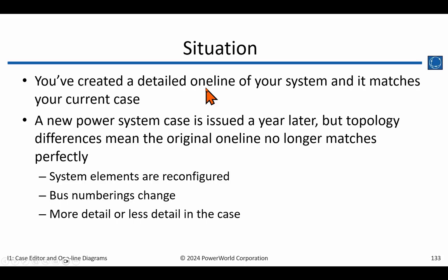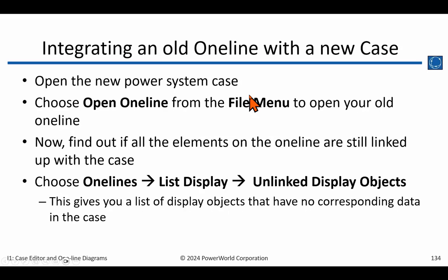Unfortunately, this is a situation that occurs pretty commonly with bus branch models. A holistic solution is to use node breaker models that don't depend on bus numbers, but rather depend on some other static key, like, for example, one that comes out of an EMS. But even with that, the reality is that people often have to work with bus branch models where the topology does change. So a couple different procedures are outlined on the following slides.